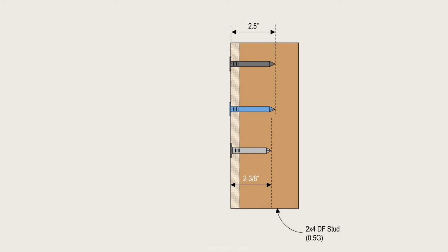As we have seen, common nails are wider than both sinker nails and box nails and longer than sinker nails. These properties also translate to superior strength for common nails when compared to the other nails. We will look at the strength of 8-penny nails attaching sheathing to wood framing. This example is intended to illustrate the importance of ensuring that designers call out the proper nail types according to the design tables in the Residential Code. Additionally, the contractor must use the nail types specified by the designer.